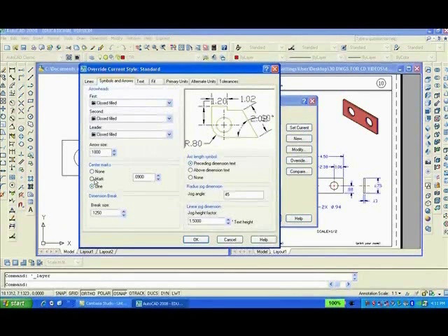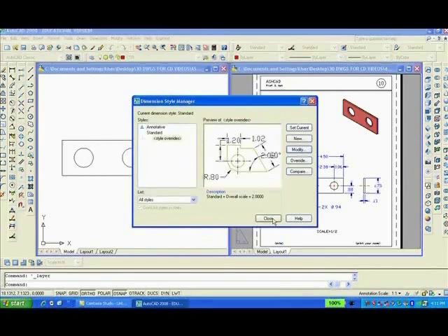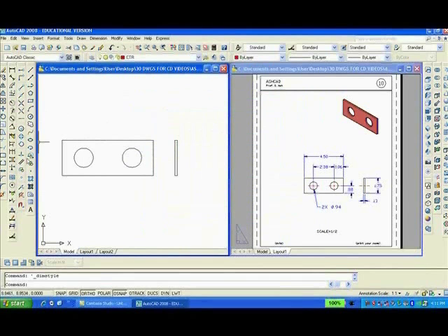Yeah, you see if I click on Mark over here, all I get is a small center mark. I really want Line to show these long center lines. So I say OK and close. Now I'll go and pick the center mark, and that's done. Repeat the command, that's done.